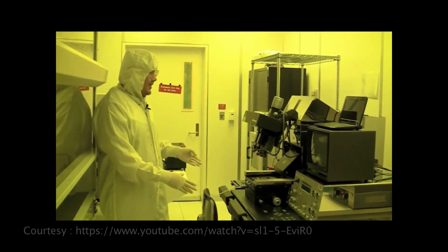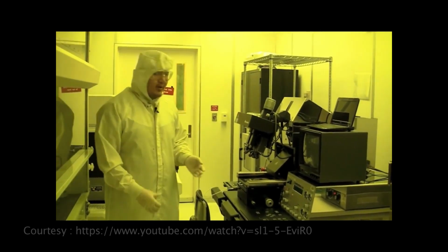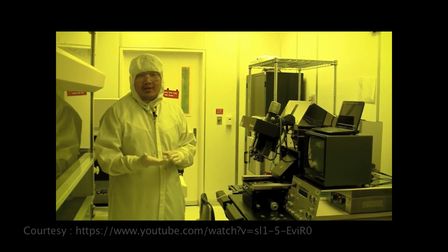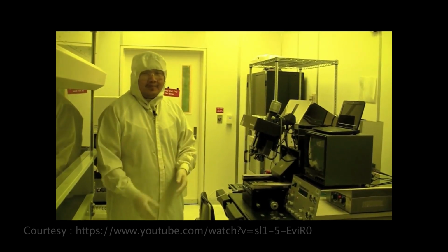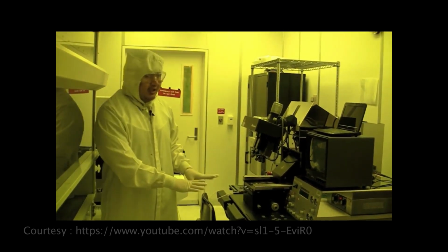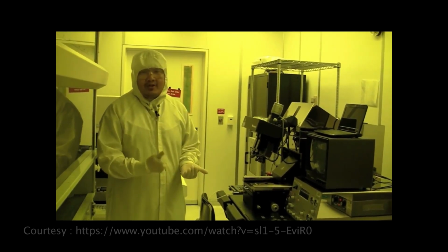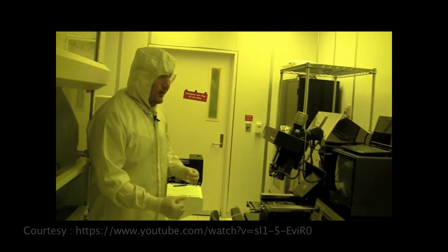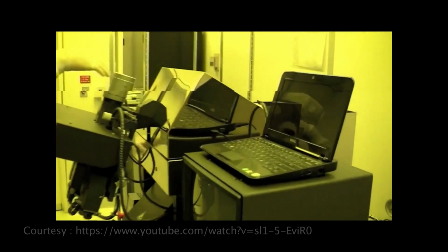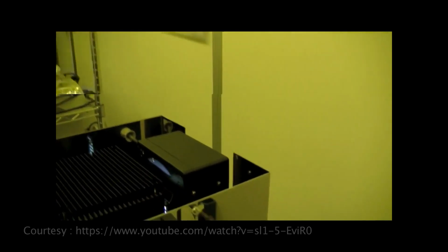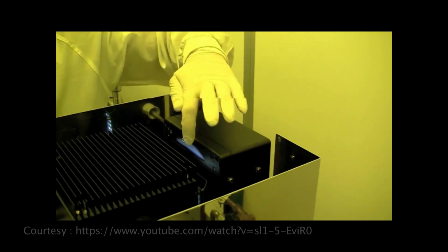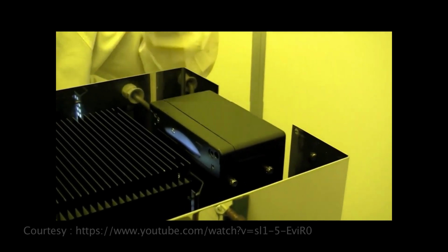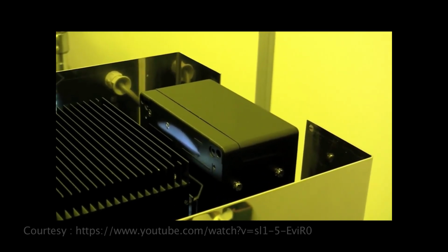This is the MA6. It's used to expose UV light to your substrate that has photoresist on it. So before we run the machine, the first thing we've got to do is make sure the light bulb is turned on or not blown up. So we come out to the back and you can see the light is turned on by the reflection here, or you can see the light glowing. So you know that the light bulb is on.